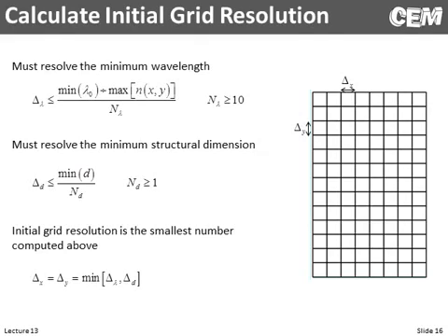However, it's taking a long time. It's up to you to figure out where that trade-off is. But convergence is the way, the rigorous way to determine these numbers. Everything else that I'm going to give you are just rules of thumb so that you can make a really good first guess as to grid resolution and stuff like that.